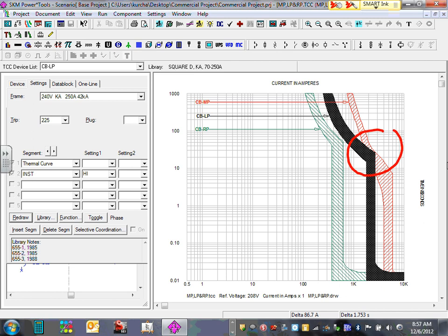Okay, take this. If you have a short circuit right here, right at this point, cool? The short circuit right at this point is going to go up, up, up. It's going to hit. Is it going to hit two curves at the same time? The way it's showing right now, are they overlapping? This means the main circuit breaker and the lighting circuit breaker are going to trip. That's it. As easy as that. Whereas if you have a good design, only one will trip. Yes. You don't want the main to trip. That's the point.